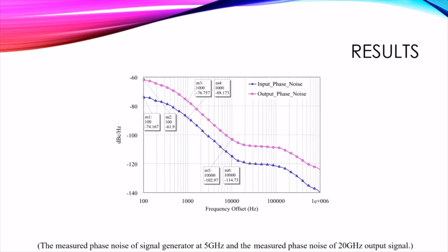Finally, the phase noise measurements are done using a UXA signal analyzer of Keysight Technologies. Since the input frequency is multiplied by the multiplying factor in frequency multipliers, phase noise increases by 20 times log n in frequency multiplier circuits in theory. Based on this formula, phase noise is expected to ideally degrade by a minimum of 12 dB in frequency quadrupler circuits.